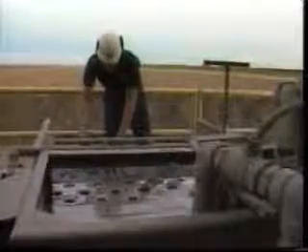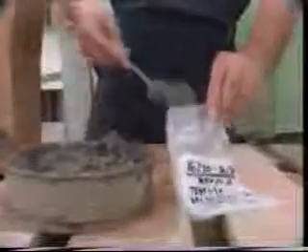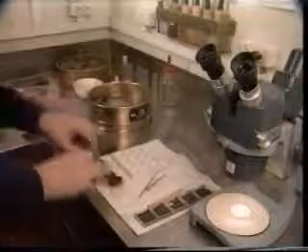The fourth function of the drilling fluid is to aid in the collection of geological information. The most obvious manner in which this is accomplished is by the transport of cuttings to the surface. By calculating the depth at which these cuttings were drilled, a lithological log of the hole can be developed.